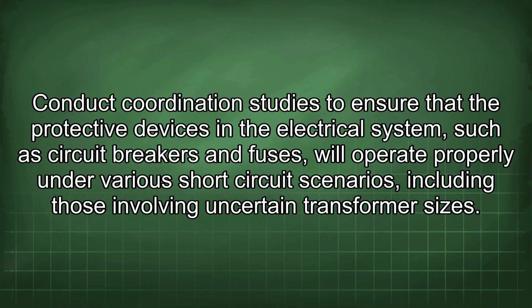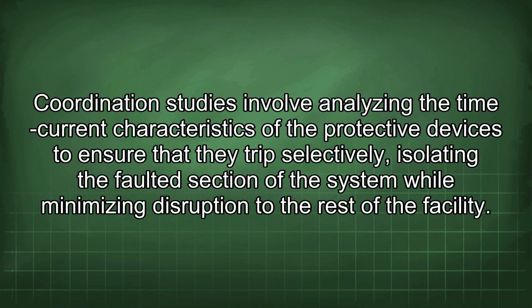Conduct coordination studies to ensure that the protective devices in the electrical system, such as circuit breakers and fuses, will operate properly under various short-circuit scenarios, including those involving uncertain transformer sizes. Coordination studies involve analyzing the time-current characteristics of the protective devices to ensure that they trip selectively, isolating the faulted section of the system while minimizing disruption to the rest of the facility.